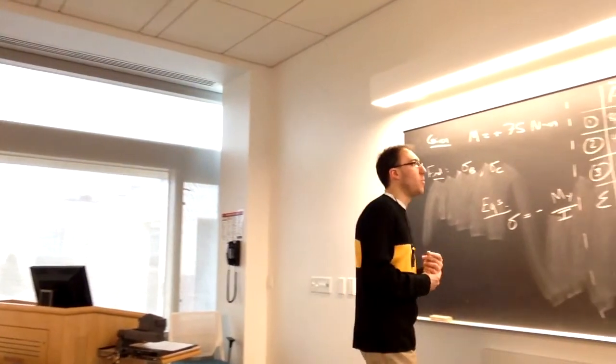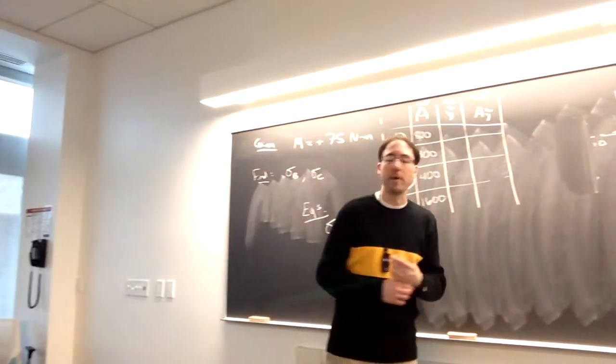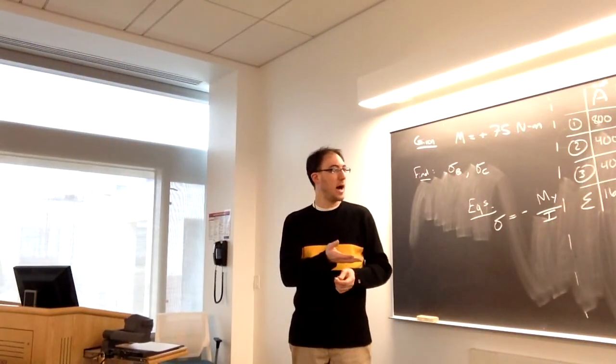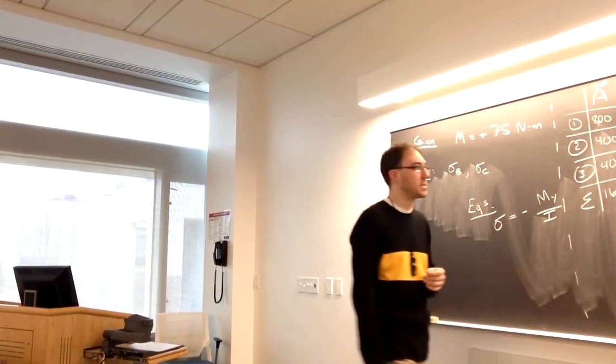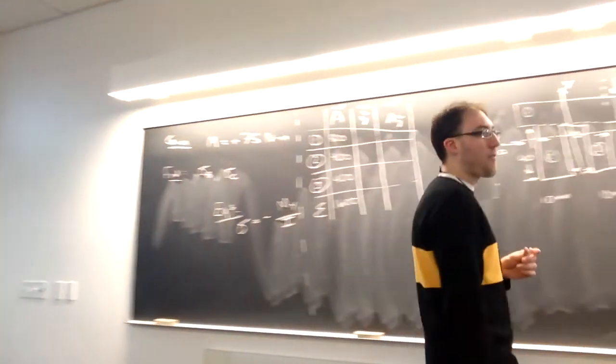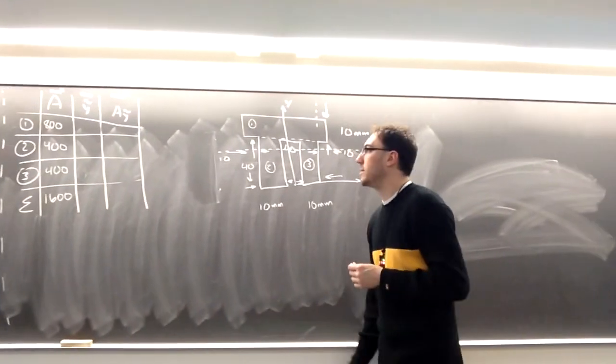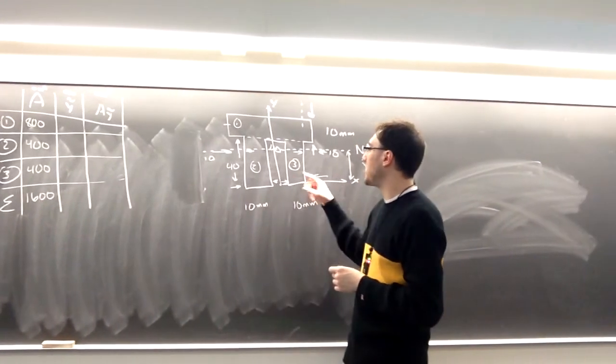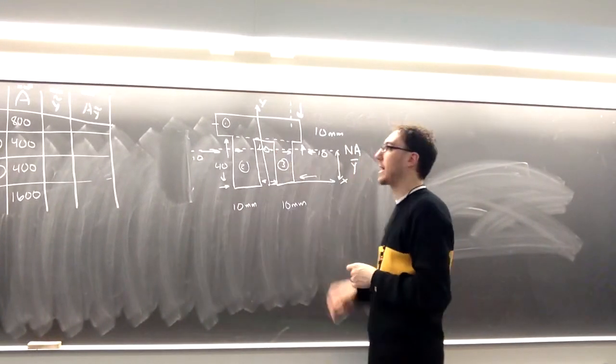We then want to find y tilde, so that is the distance between the shape's centroid and the origin of the coordinate system. So remember, for a rectangle, the centroid is at half of its height. But we have to measure that vertically to the x-axis.